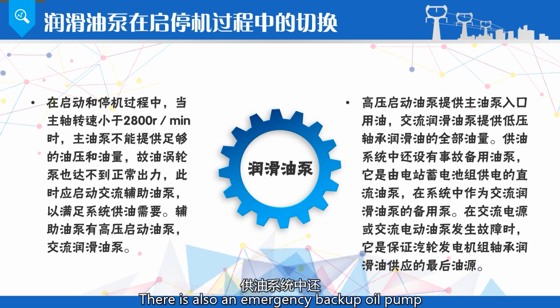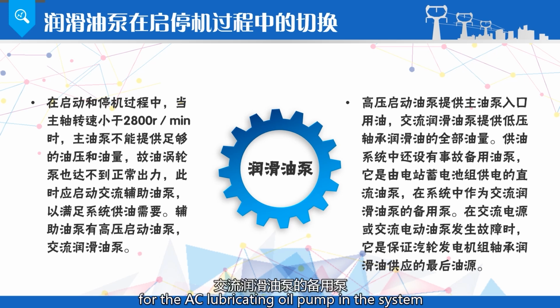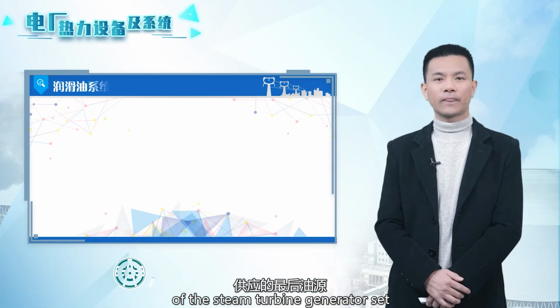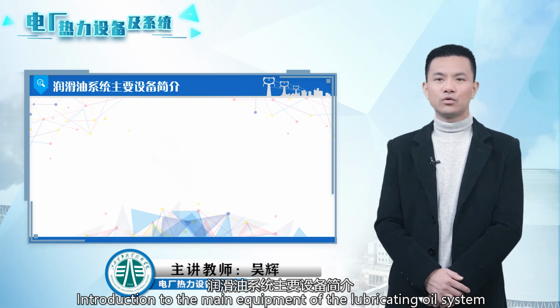There is also an emergency backup oil pump in the oil supply system, which is a DC oil pump powered by the power station battery pack and serves as a backup pump for the AC lubricating oil pump in the system. When the AC power supply or AC electric oil pump fails, it is the last oil source to ensure the supply of lubricating oil to the bearings of the steam turbine generator set. Introduction to the main equipment of the lubricating oil system.